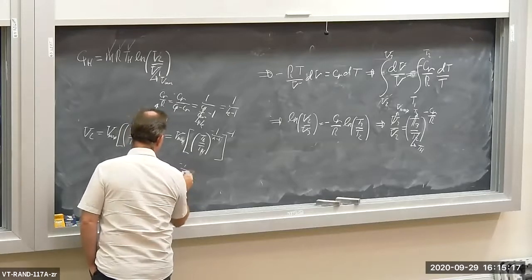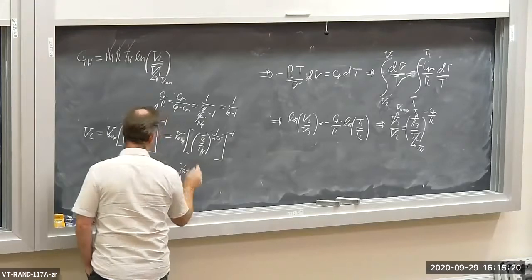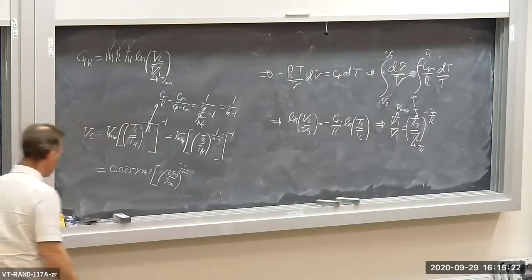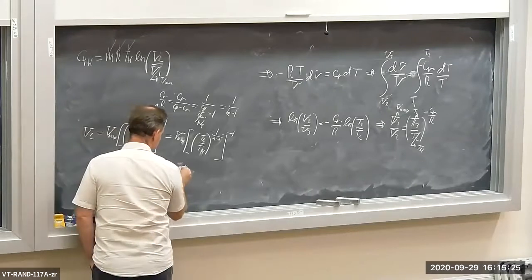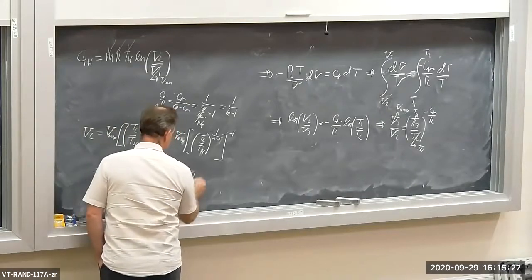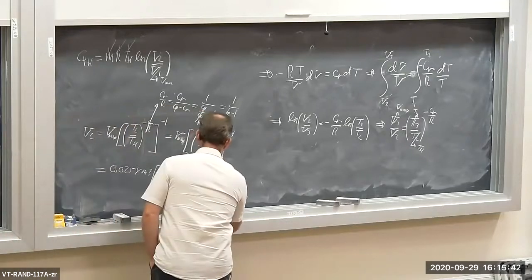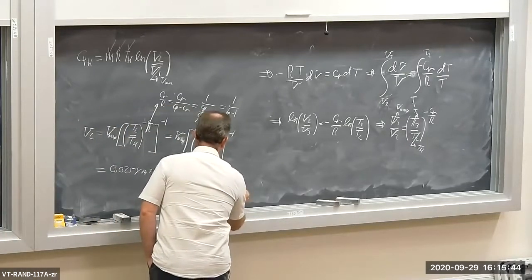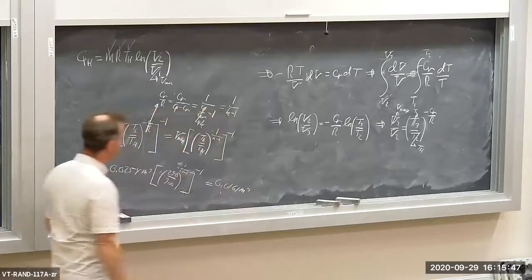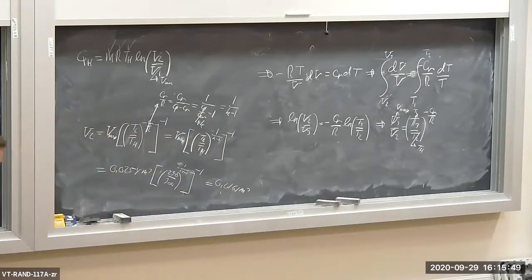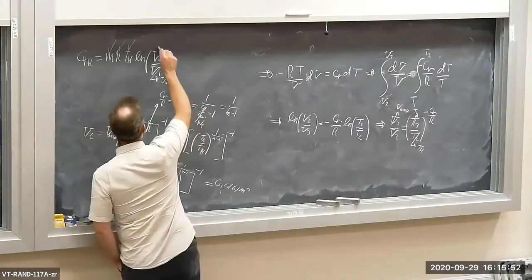And then I get minus 1 over 1.4 minus 1, and that's to the -1 power. And I get the volume at state 2. Volume at state 2 is equal to 0.0161 cubic meters. So now I know V2.